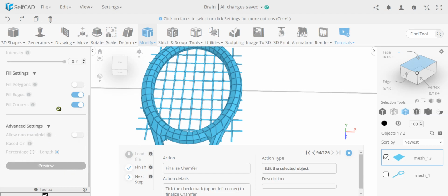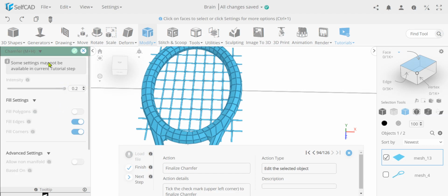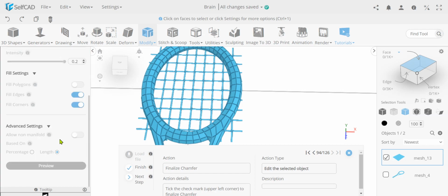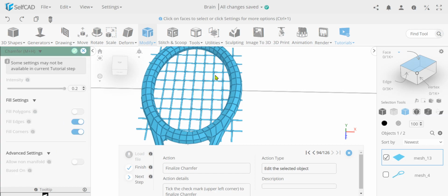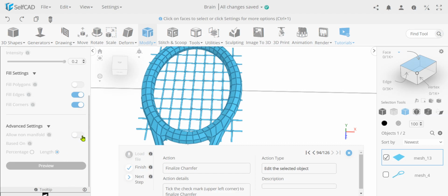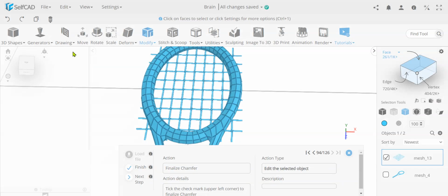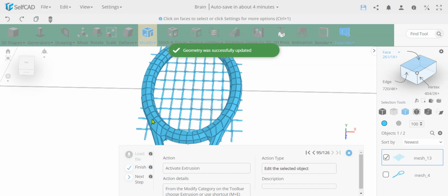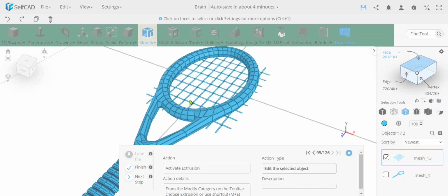But this is something that's called clipping, standard on these types of mesh editing tools, that it automatically calculates the max, and by default the clipping is on. In a mesh like this, 0.2 was the max, so it says it automatically, but if you turn this on, it could be more. Okay, so we're going to finalize it. So what we have now is this basic mesh, but there's no thickness. Again, it's just a surface because it was a plane initially, so there's no thickness.